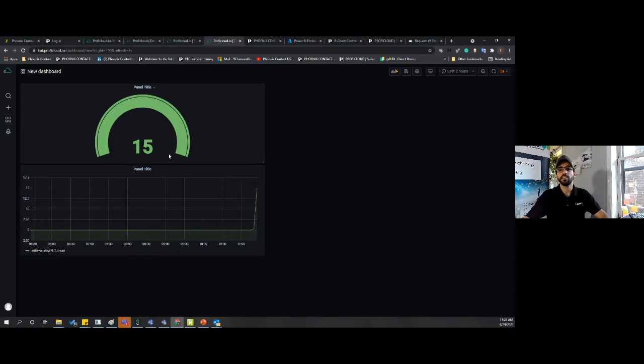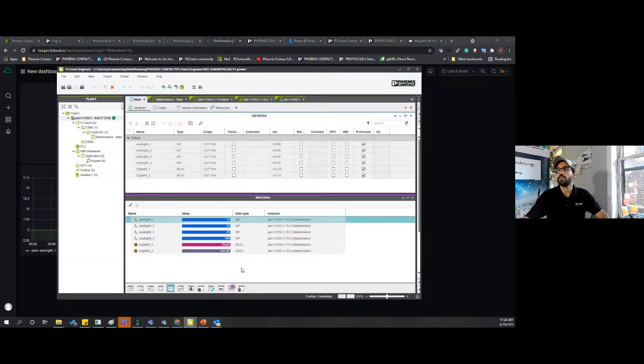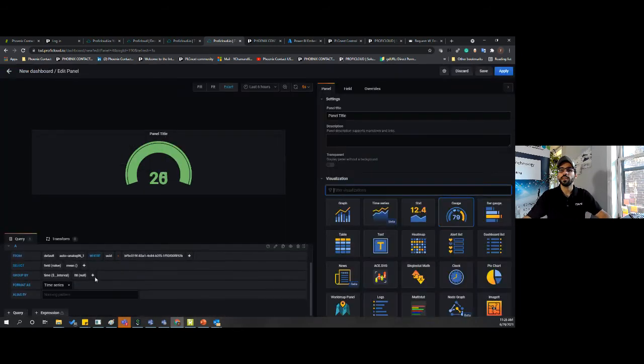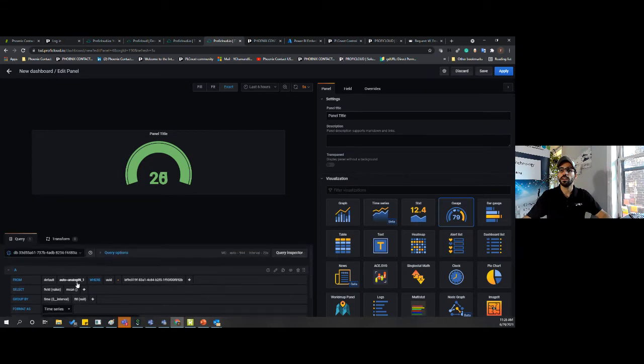value on the screen. And if I change that again, now we should be able to see that a little bit like real time. There is a delay. This is a cloud connection. It's not a runtime, PLC runtime. So that is a delay in between the change. Okay, so it's already on 25 over here. And it's showing me the mean value of it. We can play around and instead of showing the mean value, we can just show the value, and that's 25.